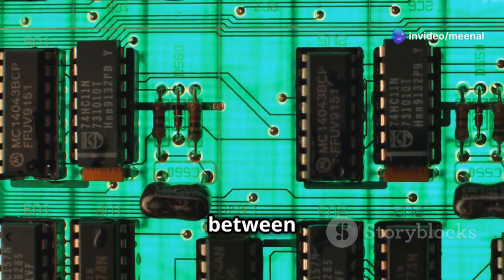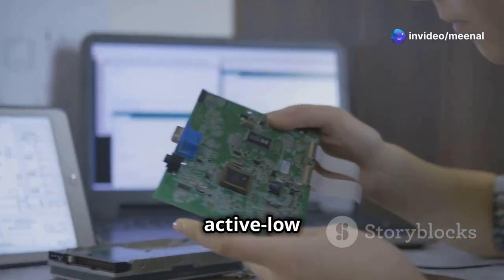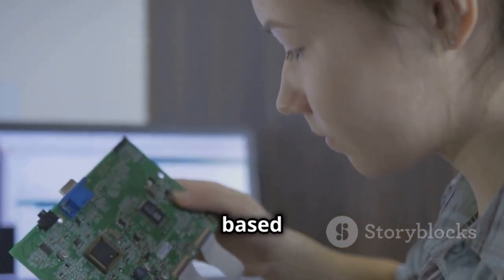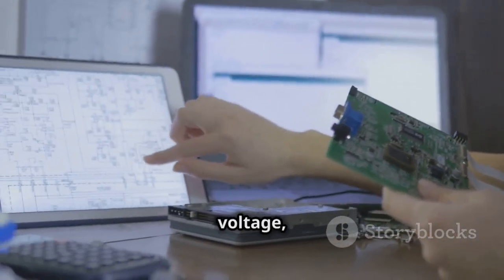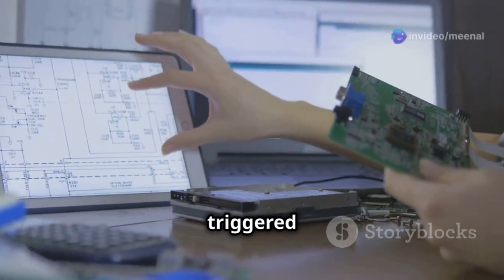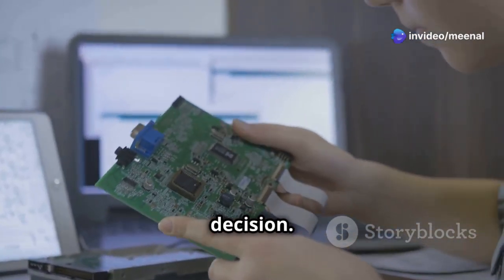Step 2. Select reset circuit type. This involves deciding between active low and active high reset circuits. Choose between active low and active high reset circuits based on your device's requirements. Active low circuits are triggered by a low voltage, while active high circuits are triggered by a high voltage. Understanding the behavior of your device will guide this decision.